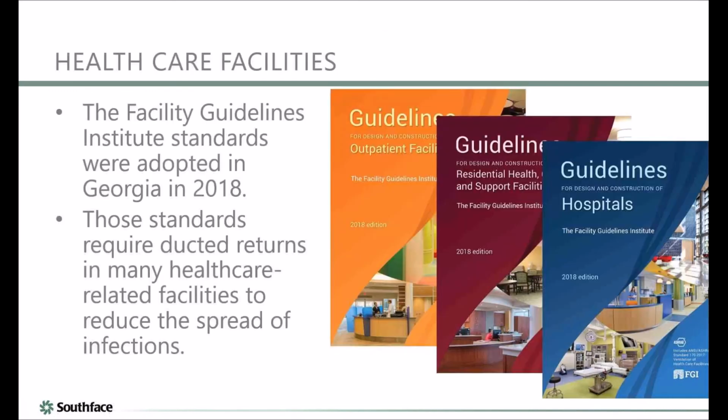This is a new one, though, and kind of interesting. I'll reinforce the importance of ducted returns. Hospitals and outpatient facilities adopted the facilities guidelines by the Facility Guidelines Institute in 2018. They require ducted returns in many healthcare-related facilities, primarily due to the spread of infection.